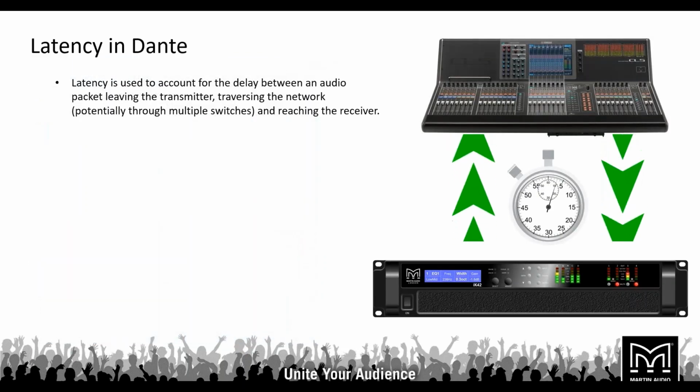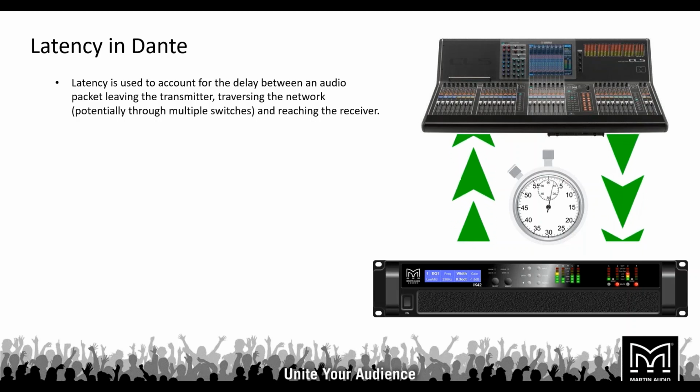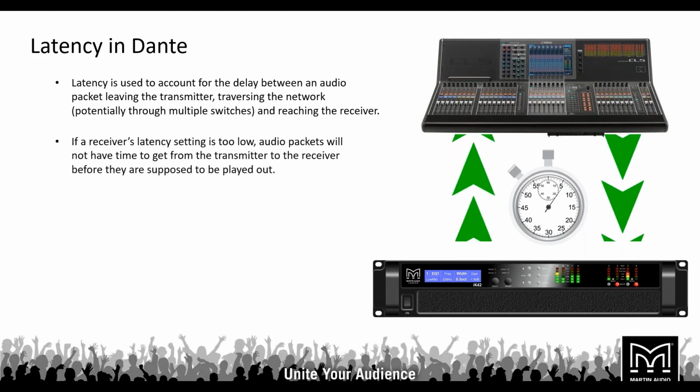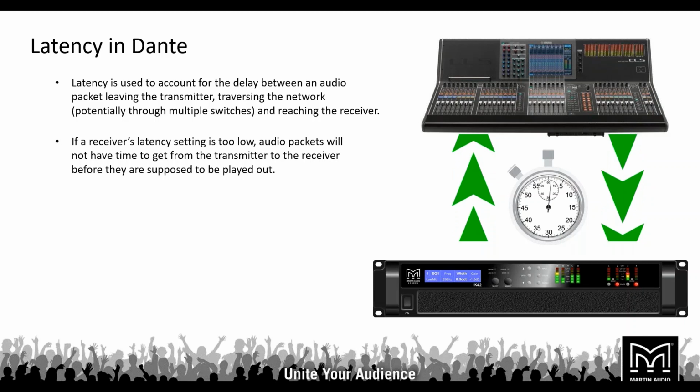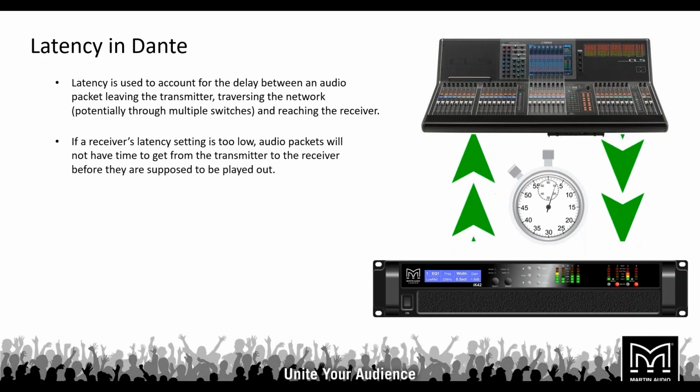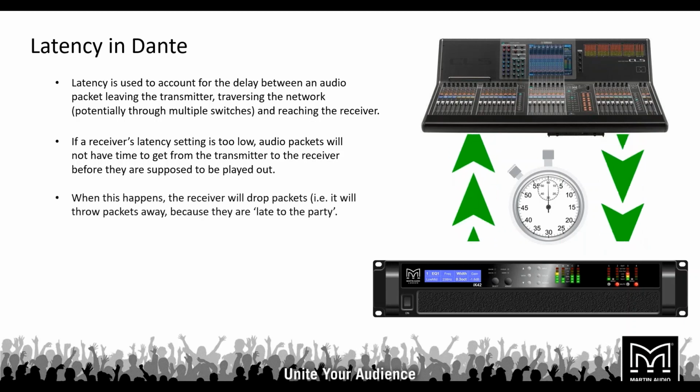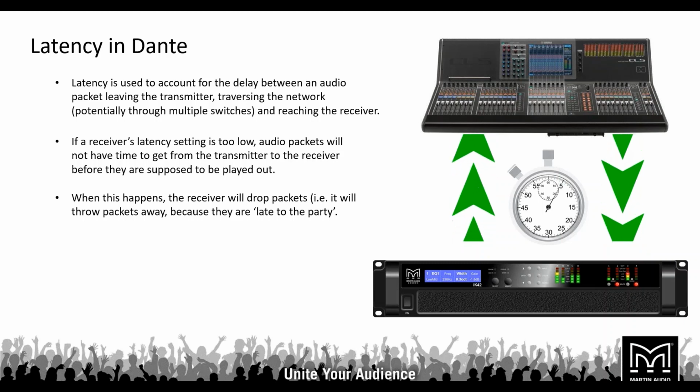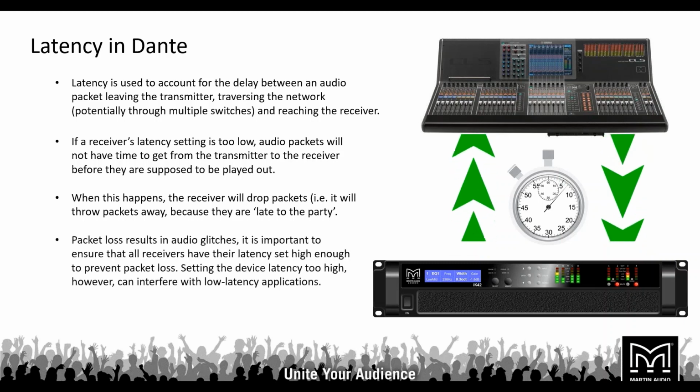So the next thing to look at within these devices is latency. This is to account for delay between audio packets leaving the transmitter, winding their way through a network and reaching the receiver. If a receiver's latency is set too low, we could lose audio packets. And when this happens, it's effectively saying we haven't made it to the receiver in time, so we're going to end up having some audio glitches.